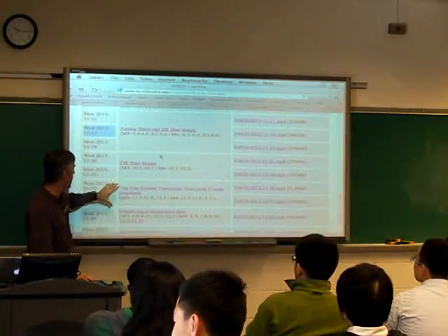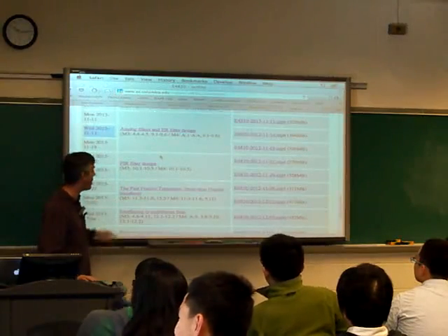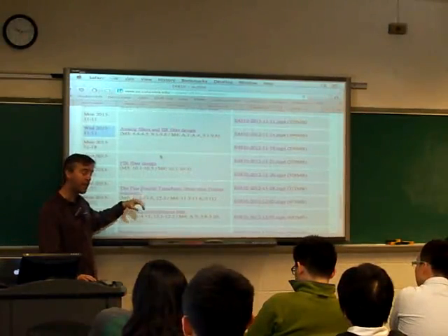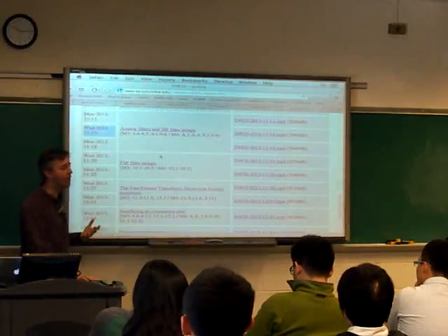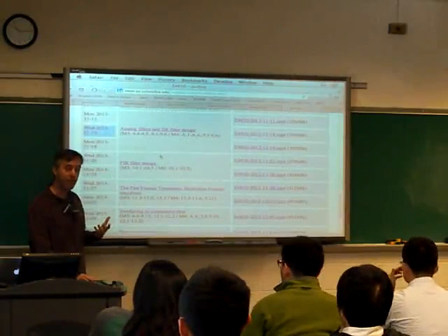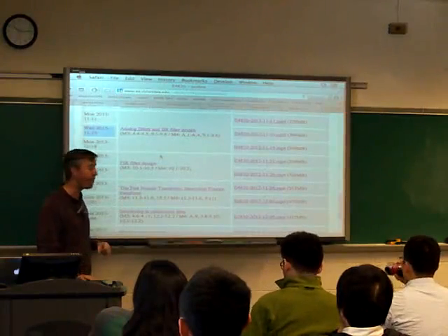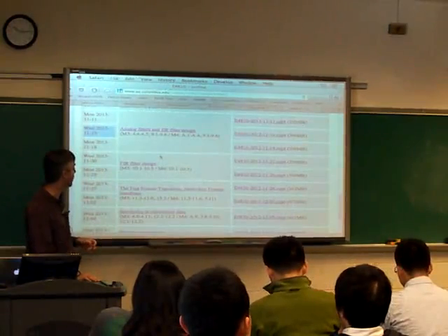And then we loop back to the DFT, and we examine this particular algorithm for calculating the DFT, the fast Fourier transform, which has a huge impact. It means that a lot of things that would be computationally infeasible we can now do in the transform domain, because there's a quick way of calculating what looks like n squared multiplications to get a discrete Fourier transform.